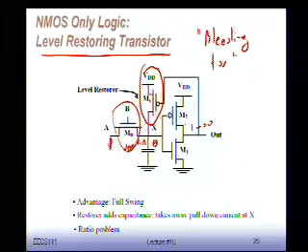So you've done your job, you switch the gate, now I'm going to pull the output node, or this intermediate node, all the way up to VDD. Now as you can see, this is again a very nice example of a feedback loop. We feed back the output signal towards some of the intermediate nodes to get full swing, right? That's a kind of nice thing, a very popular design strategy. A lot of designs will use exactly this approach. The little feedback loop, bingo, node goes all the way up, we're done, all problems are solved.